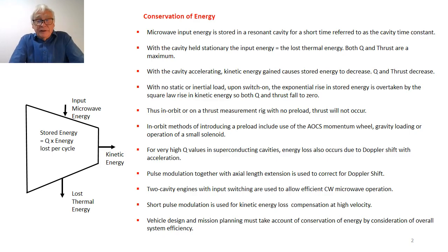Once you apply just a very small amount of mechanical preload, then the rise in kinetic energy, which theoretically is at almost infinite rate if there's no preload, will very rapidly drop off, and it enables the stored energy rise to maintain above the rise in kinetic energy.